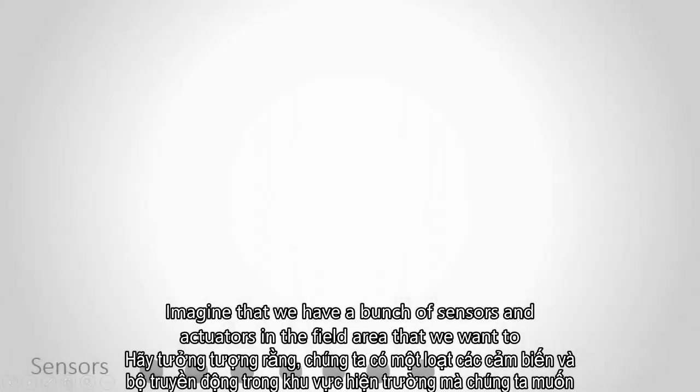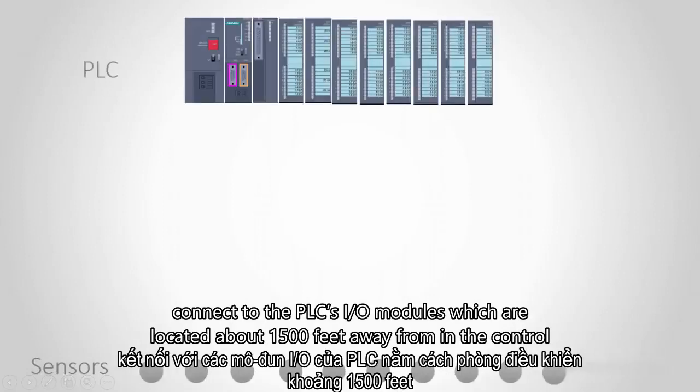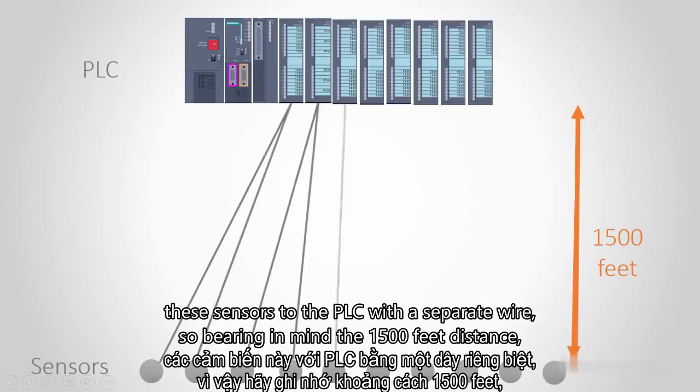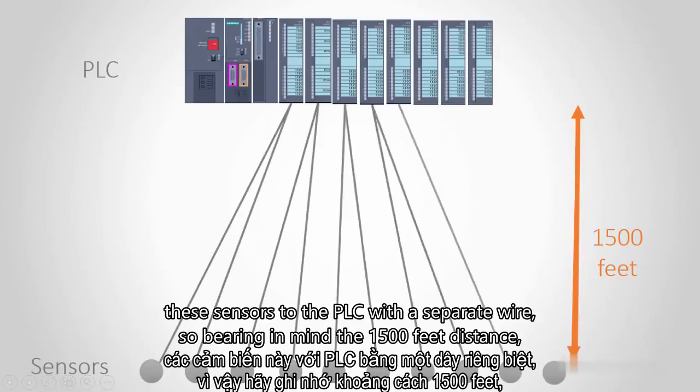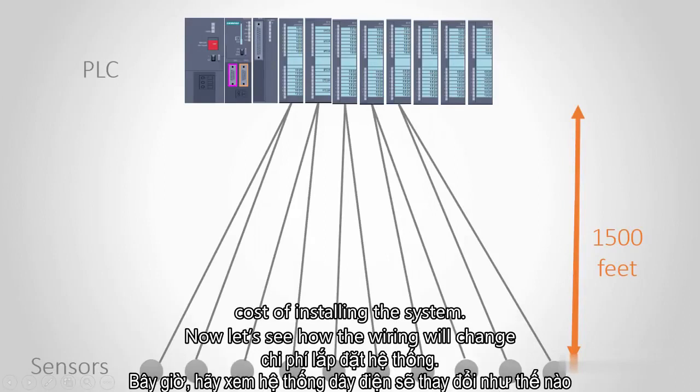Imagine that we have a bunch of sensors and actuators in the field area that we want to connect to the PLC's I/O modules, which are located about 1,500 feet away in the control room. To do this, we need to connect each one of these sensors to the PLC with a separate wire. So bearing in mind the 1,500-foot distance, we're going to end up with a huge number of parallel wires, and this can increase the cost of installing the system.